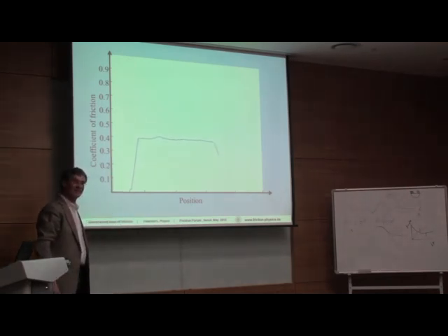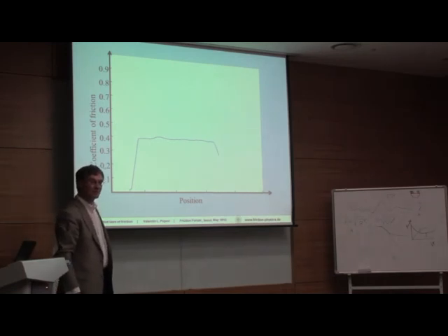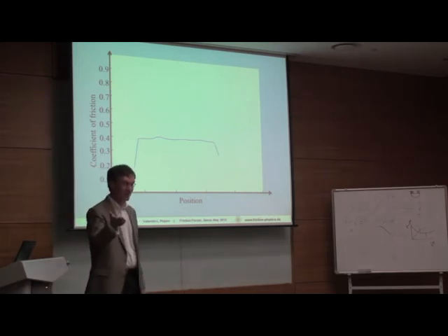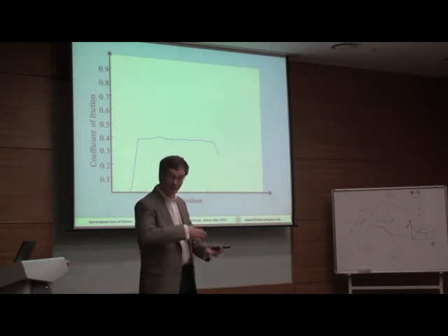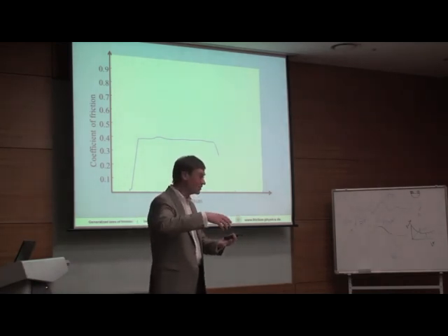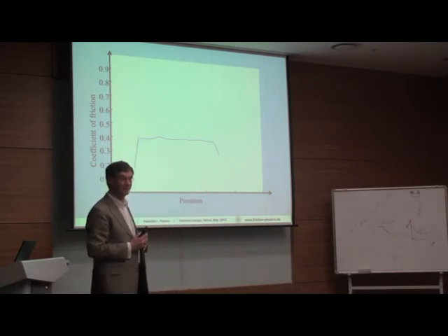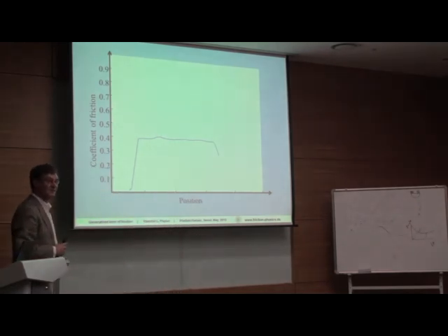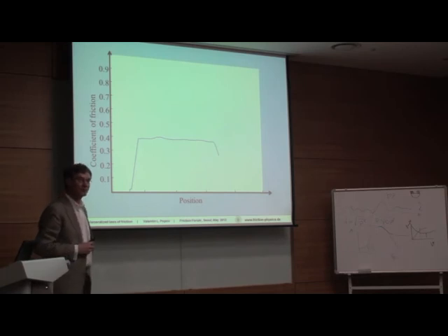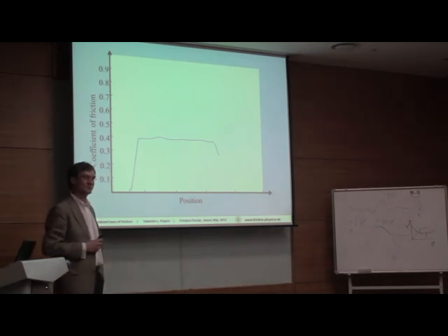What you're doing now, you're putting history into the wear path. Yes. So you're running along the path. Of course, it is in principle what Ostermeyer described on the larger scale, with wear debris and everything. Something like this is happening here. In this case, you're burnishing it because you've got a steel ball, minimal wear. You've got a polyurethane, which is not going to really wear. It's going to burnish. And depending upon the load, you're just going to burnish a path backwards and forwards.